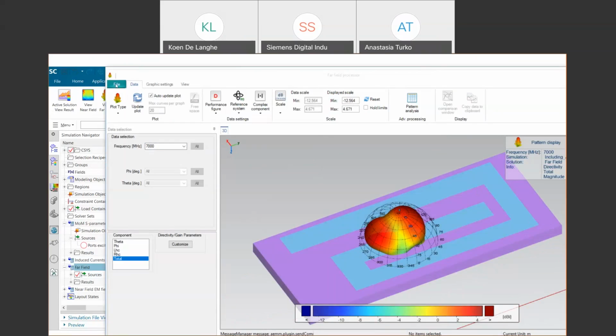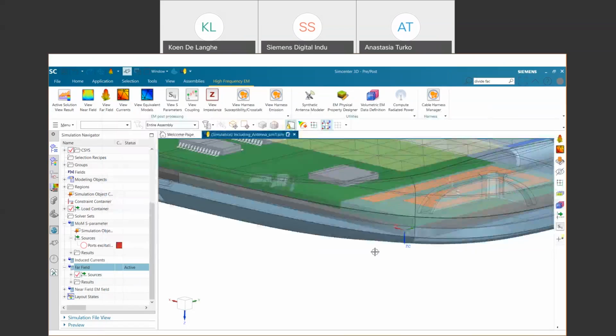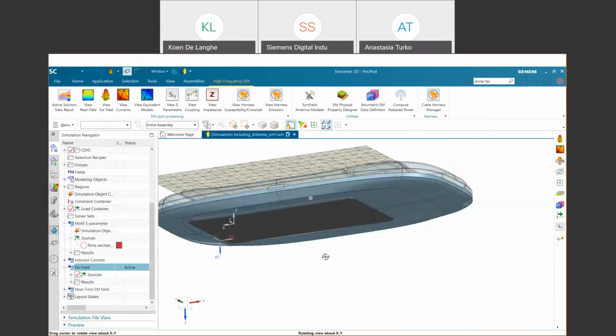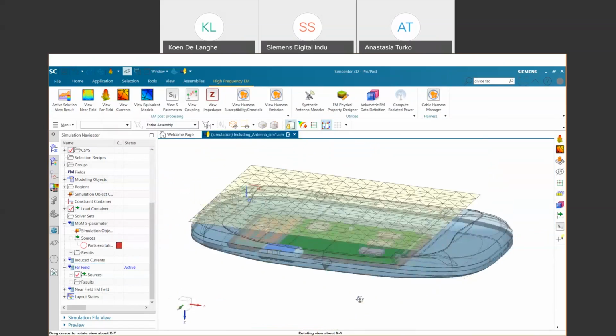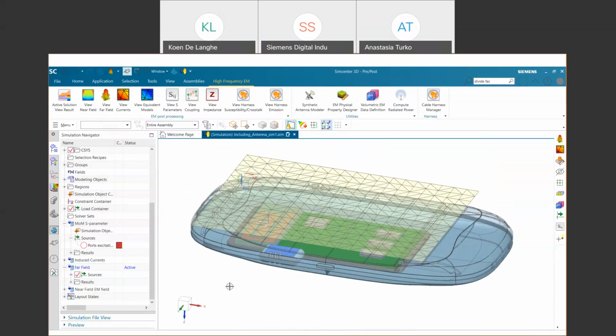Koen? Okay, so this is basically the demo of the antenna for that device. Just to resume, we can design the antenna. We can design the system inside it, the casing, right? That casing is an MCAD system, with full design capability. And we have the solver technology to calculate S-parameter and directivity or near field and so on. We can, of course, also include antenna matching impedances.